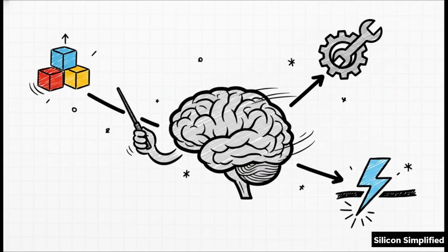So the test operates as the chief orchestrator, right? And it holds 3 massive responsibilities. First, it literally brings the top-level environment into existence. Second, it configures that environment. Maybe it's tweaking parameters using the factory or the configuration database to suit a specific test scenario. And third, it applies the actual stimulus by invoking sequences. It is the brain of the operation, directing the entire flow from the very top.